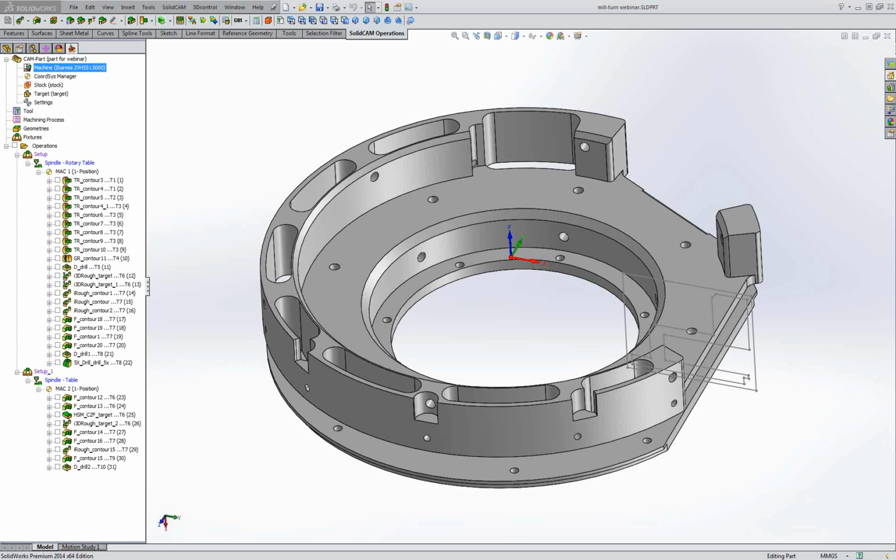Today I selected another example. In the past we defined these machines only as milling machines, 4 or 5 axis milling machines. Today all those older series machines, 4 and 5 axis milling, become mill turn machines. Why? Because the manufacturer adds a spinning option on the table, on the 4th axis, and you get a new series of mill turn. And we call them milling machines with turning option.